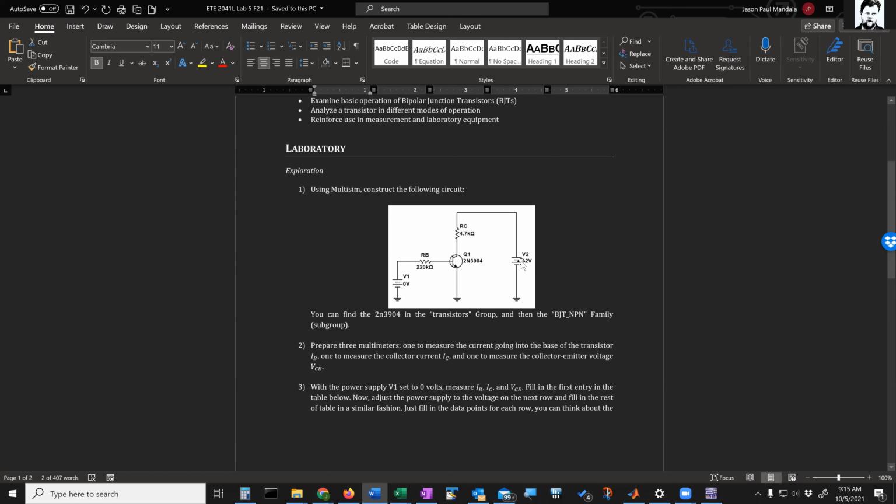this resistor. And then as you increase the current more, as you increase the base current, you're increasing the collector current. So the collector current will increase, the voltage across this resistor will increase. And that means that the voltage across the transistor will be decreasing. So if initially you had 12 across the transistor and 0 across the resistor, as you increase the current, the transistor voltage will be going down and the resistor voltage will be going up.